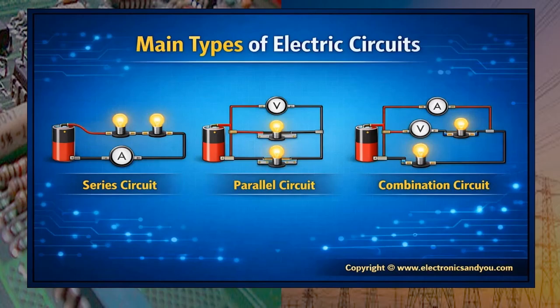And it's opposite to voltmeter. Voltmeter, if you want to measure the voltage in a circuit, you connect it in parallel with the components to measure the voltage across the components. Why? Because when you compare the circuit later, you will see that in series circuit the current is constant while voltage varies from load to load. In parallel circuit, the voltage is constant across all the loads connected in parallel, but the current differs in each of the branches.